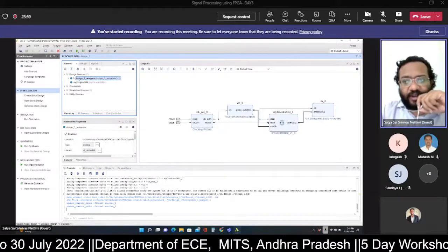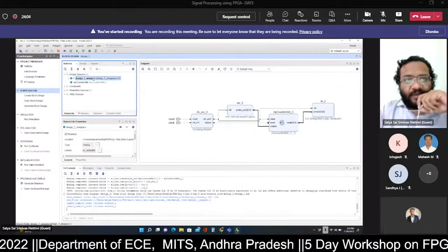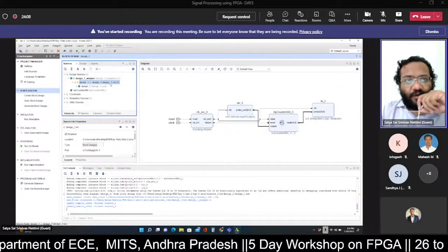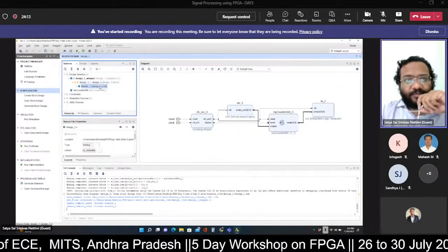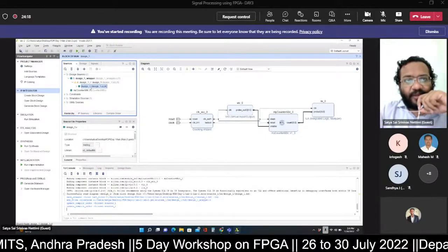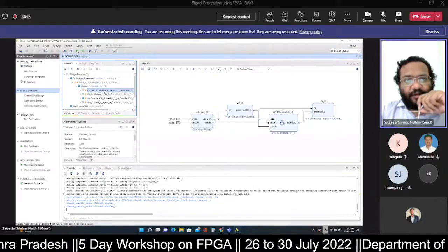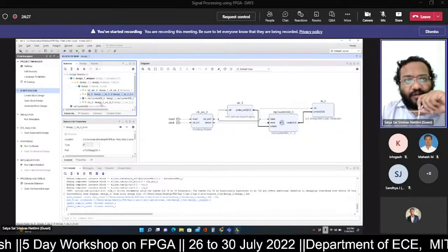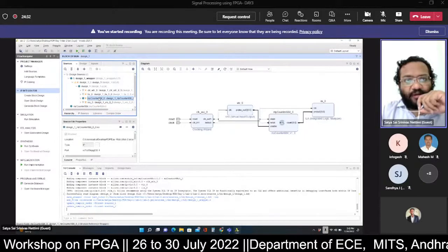The wrapper file name goes as follows: design_1_wrapper. If you open this hierarchy, within the wrapper you have a block design. And within that block design, you have the corresponding Verilog file, that is design_1.v. Again, if you open that, you have a separate IP block for clocking wizard, for ILA IP core, for VIO IP core, and a block design for your counter.